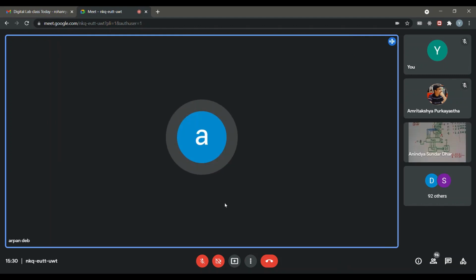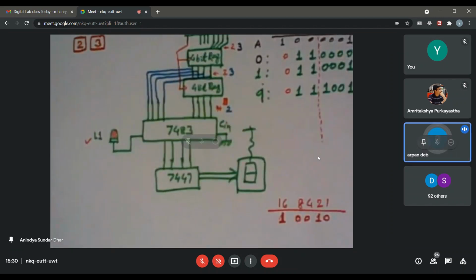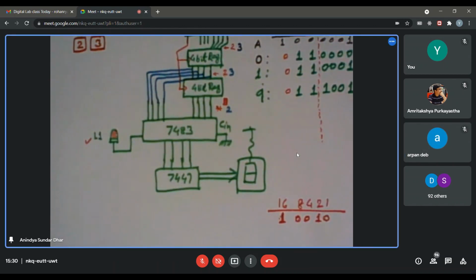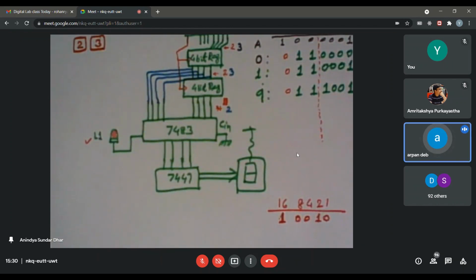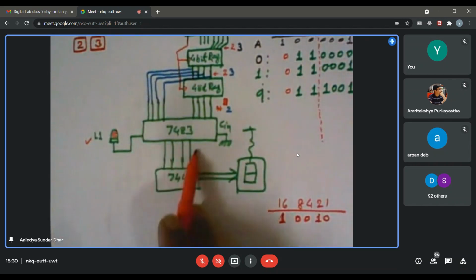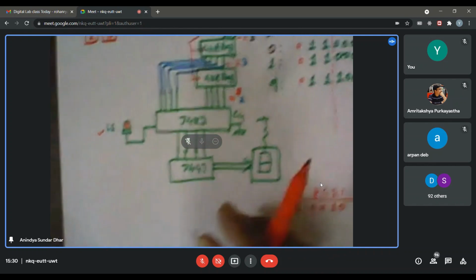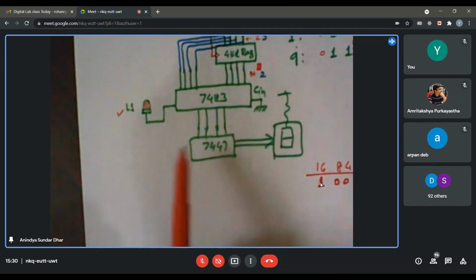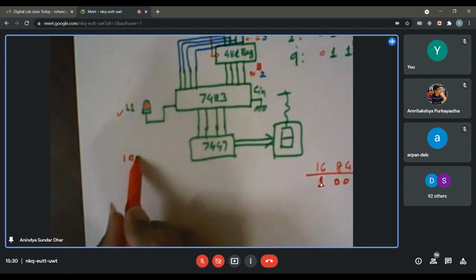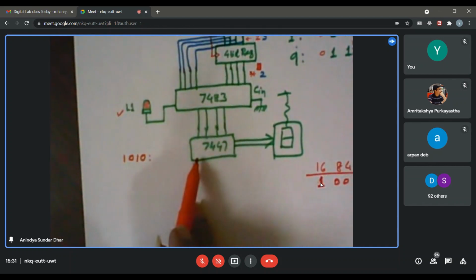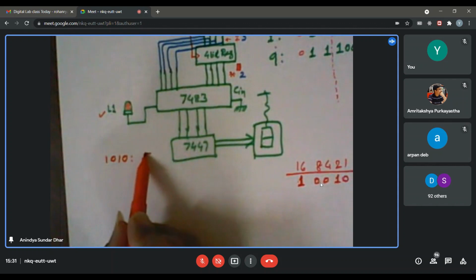Like for outputs like 12 and 13, then I think like inverted C, those figures will be displayed only in this case. Come again, I could not follow. So like now if the output is 12 or 13, then what would be the display? Now you are saying, okay, so if it is within this 4-bit value, there won't be any carry. For example, if I press 9 and 1, it will be 10. Then the output code here will be 1010, and if you feed 1010 to 7447, I hope you recall, it will look like this.